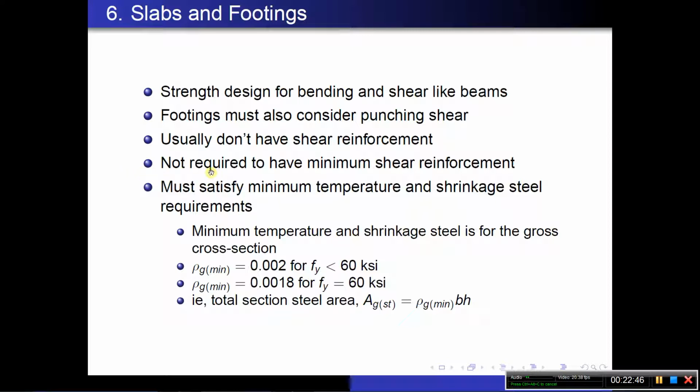The other thing is that there are some minimum shear reinforcement requirements in the code, but slabs and footings are a place where there is an exception to those requirements.